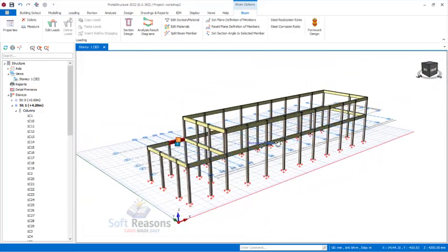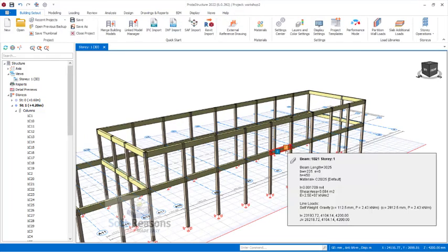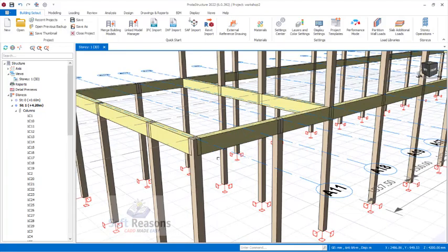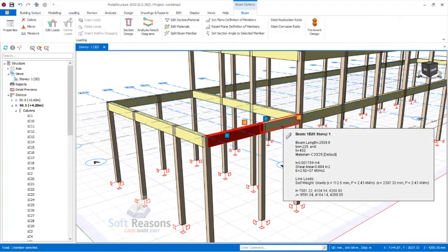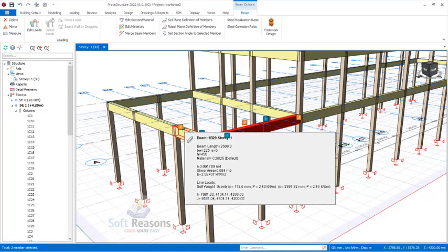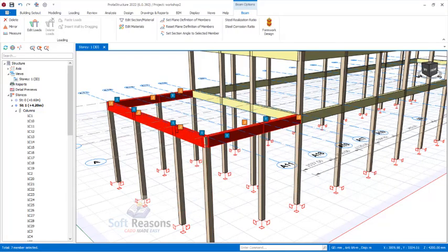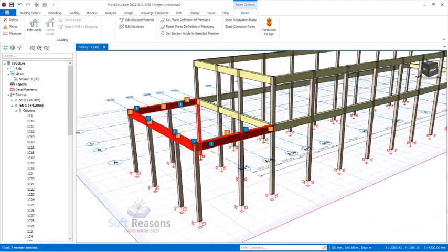After which we will now be working on the beams in terms of the beam depth. At these provisions where we have the workshop, I will hold the control key to select multiple beams. I want to change the depth of these, because they serve as roof beams at this particular part of the structure.